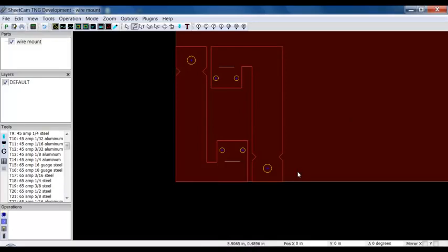Okay. In SheetCam, you cannot change the size of an object. Okay. And you can't erase parts of an object. But what you can do is tell it to cut part of a file and not other parts. Okay. So with everything on one layer, when I generate an operation, it will cut everything on that layer. Okay. And according to which type of offset I select.